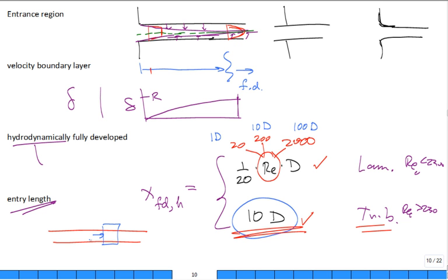Fully developed. I mean, the manufacturer of the flow meter is going to test it, but they're not going to test it on the 1,000, 10,000 different configurations that you could have in the field. They're going to test it on the one configuration, which is a long straight pipe before it hits the flow meter, indicating that it's going to be fully developed flow before it hits the flow meter. And most of the time it's turbulent, fully developed flow, right?